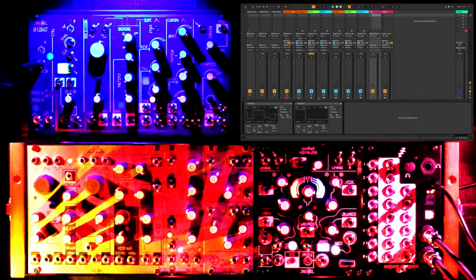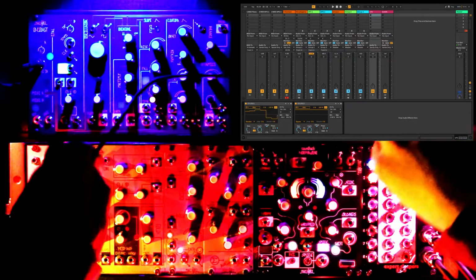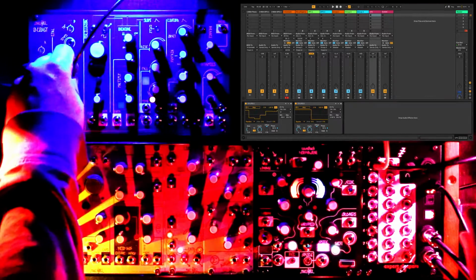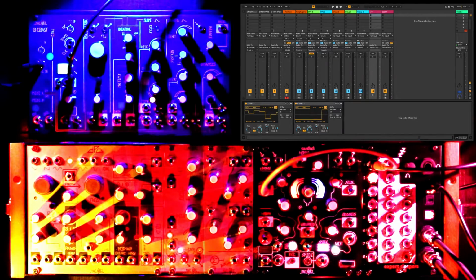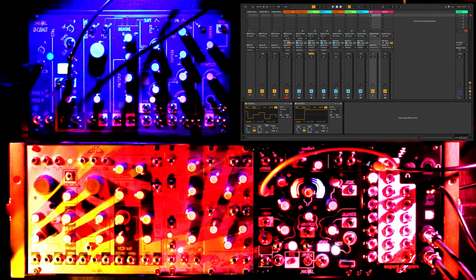Let's switch on our first LFO and route it to the first CV output on the ES9, and we'll route the second LFO to the second CV output. Note that CV outs 1 to 8 on the interface are seen as outs 9 to 16 in Ableton. Here we're using a stackable cable to send the random LFO to the Zero Coast's attenuverter to be used later, and the gene size input on the Morphogene, which controls the size of the playback window.